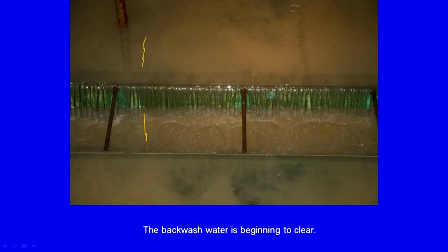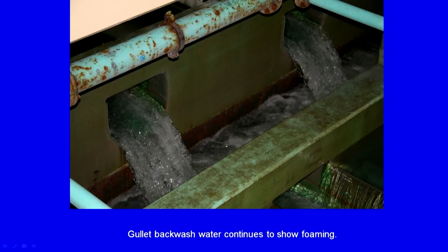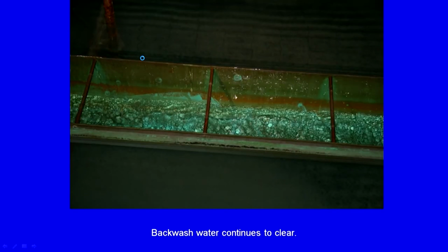And again, after more continuous backwashing, the backwash water is starting to become relatively clearer, meaning the filter is relatively cleaner now. And the backwash continues to show foaming, which means there is still organic matter that is taking longer to desorb.